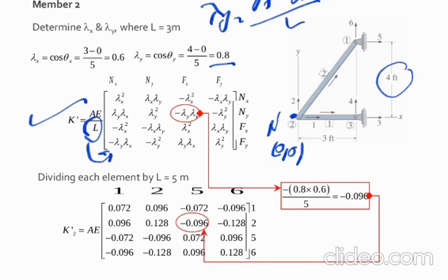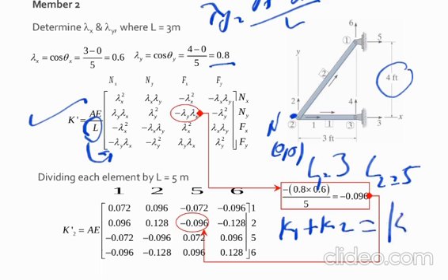because when we collect matrix number 1, that means k number 1 plus k number 2, we already have different lengths. As you remember, the length of number 1 is 3, and the length of number 2 is 5. So maybe we would face some confusion when we calculate K1 and K2. So it's easy for us to put L inside the matrix.